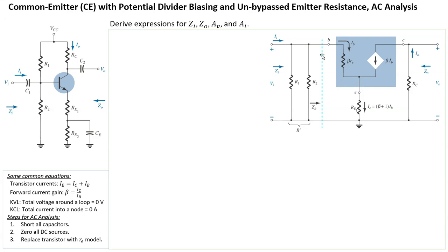And because it's not quite like the other circuit that we had where there wasn't an emitter resistor, since there is one for this case, it's not a straightforward combination of these two resistors. So we need to have another impedance called ZB, B for base. So it's a base impedance, if you like. That means the impedance looking into here, looking into the base.